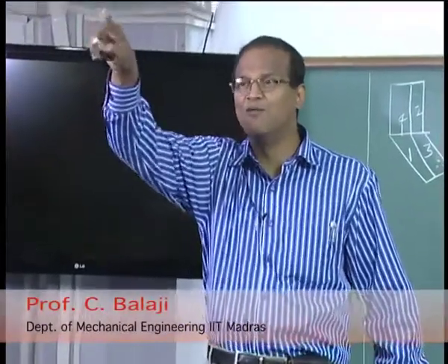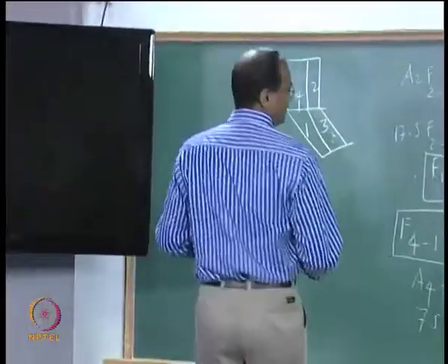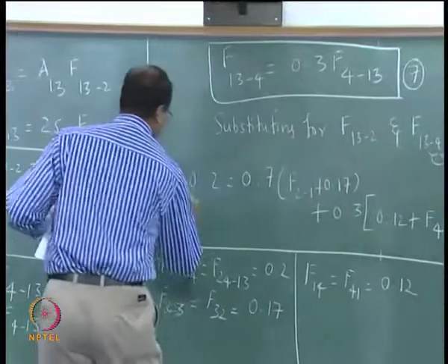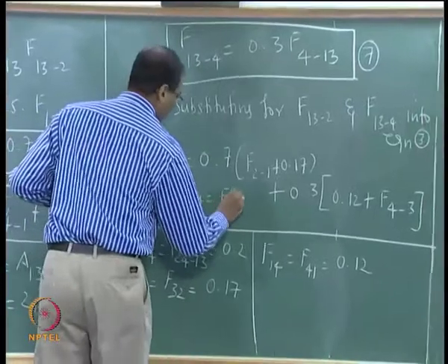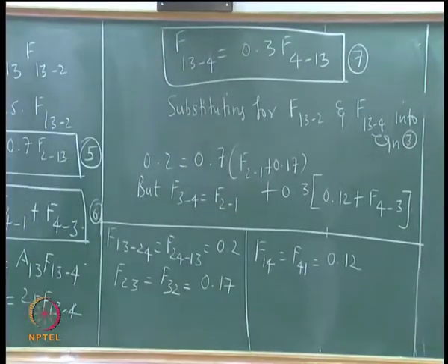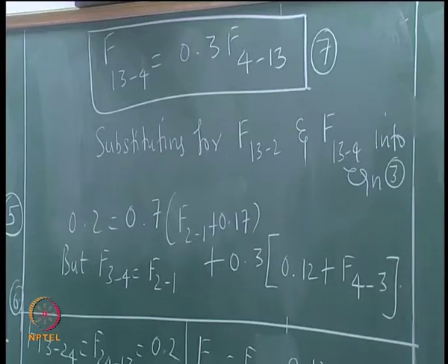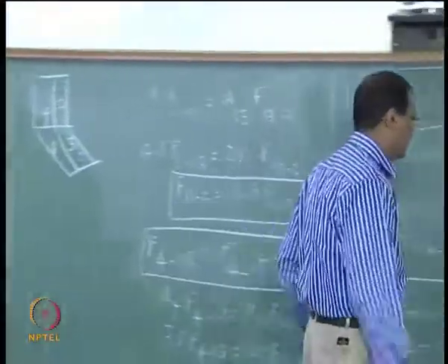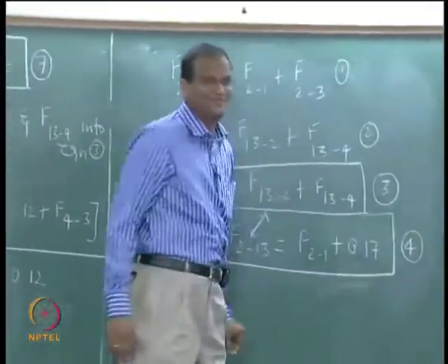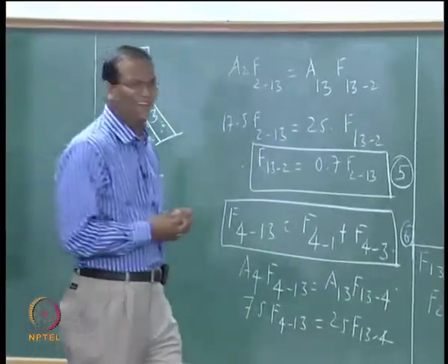That is where you reduce the number of unknown factors by 1, okay. But the critical step now is F34 equal to F21. So shall we give a name to this? Law of corresponding corners. This is called the law of corresponding corners. Okay. It is important to give a name so that you do not forget.